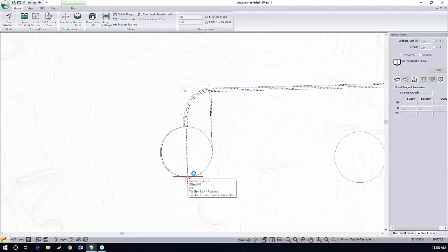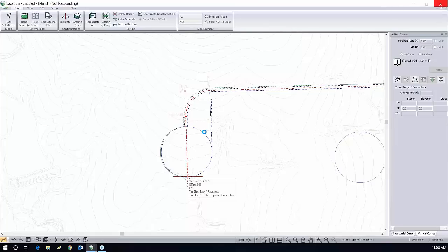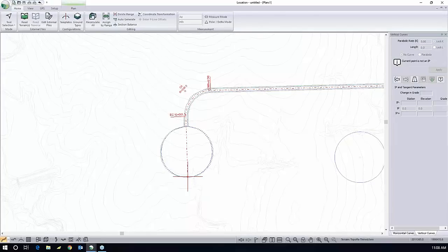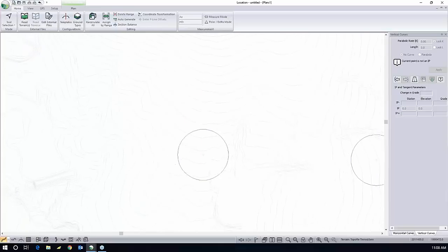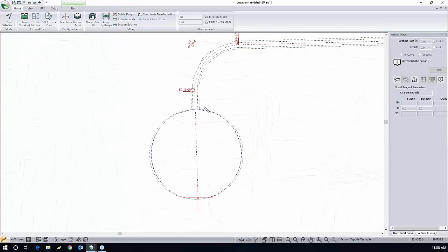Move the road back a little bit more. There, that looks better. Okay, so you can see that the road edge is just snapping right to that reference feature all the way around the pad. And there's slope stakes that you can see coming around. So that's top of cut, toe of fill, all the way around the pad. I'm going to put a reference point on the pad right here.